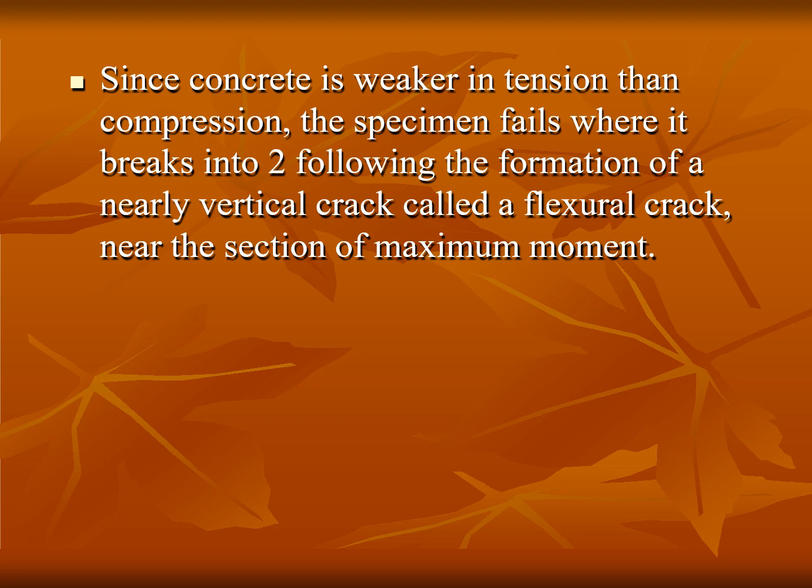Since concrete is weaker in tension than compression, the specimen fails and breaks into two parts. A nearly vertical crack, called a flexural crack, occurs near the section of maximum moment in the concrete. These are the destructive tests for finding out the tensile strength and compression strength of hardened concrete.